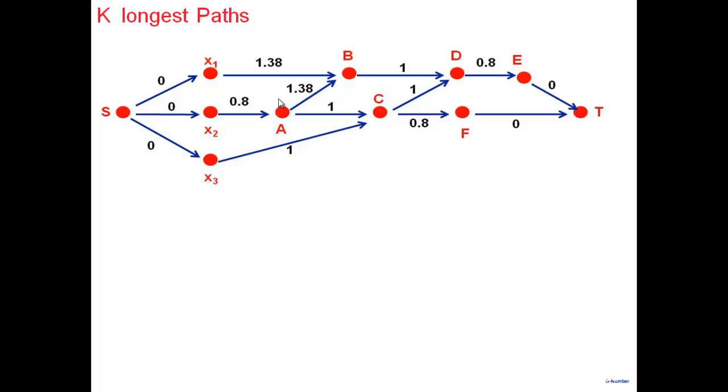That's the only source of delay in all these circuits. So the NAND gate will be made up of transistors. Transistors will have capacitances. Wires will have capacitances. And when you go from 0 to 1 or 1 to 0, the capacitors will have to be charged or discharged. Delays will come from there. So what am I putting here then?